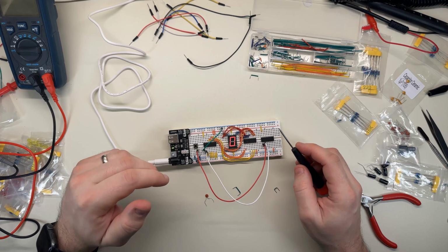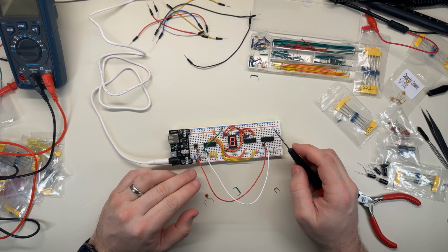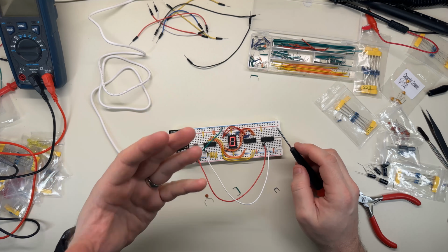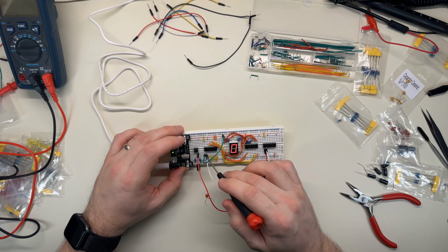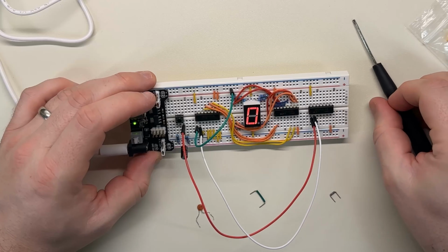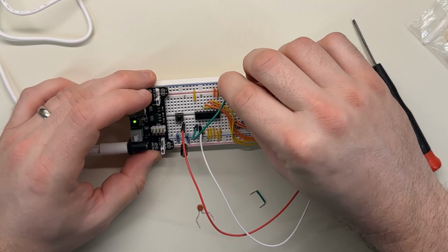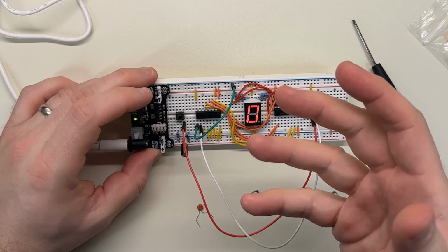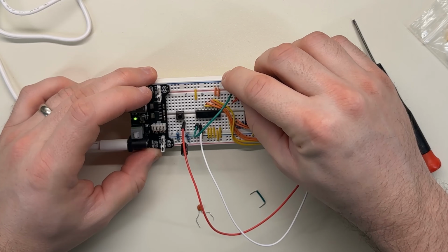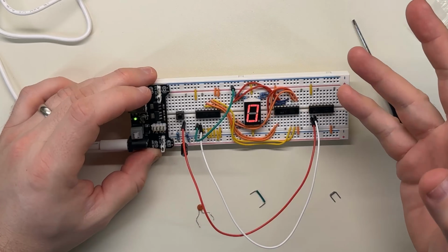When you first turn it on, the capacitor is going to fill up, and that takes a moment, right? And during that moment while it's filling up, what if we could hold the reset pin low so that it's permanently in a state of reset until the capacitor gets full, at which point the voltage ends up being high, and it'll stop resetting.